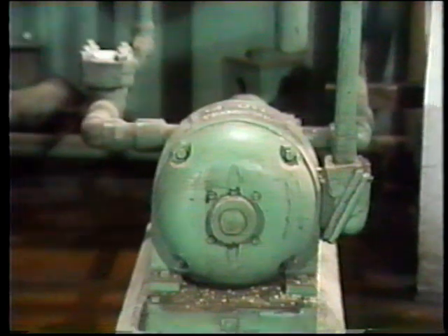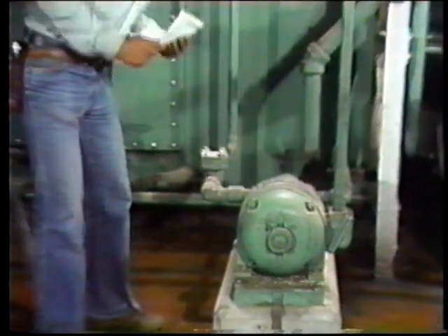That means the first thing Bill has to do is go to the motor and check out the nameplate. He needs to verify that these conductors will do the job. In other words, he's going to make sure the size 12 conductors meet the amperage requirements and the voltage requirements. And he's going to have to check out the temperature and the location of the job site. Okay. What does the nameplate on the motor say?